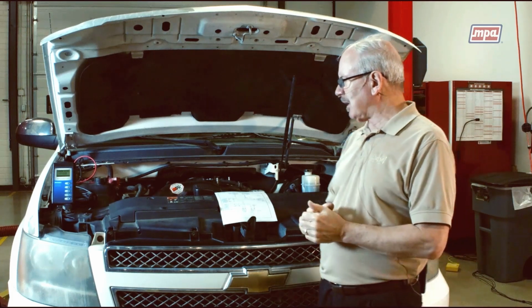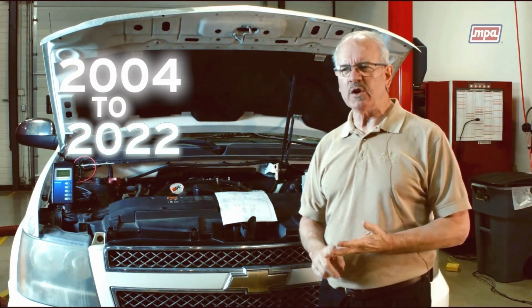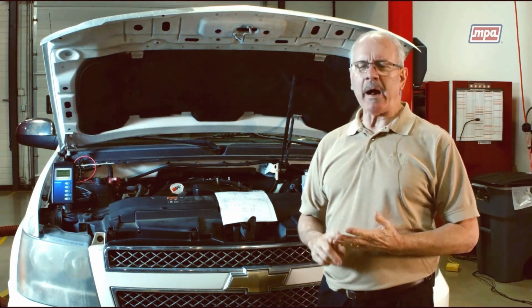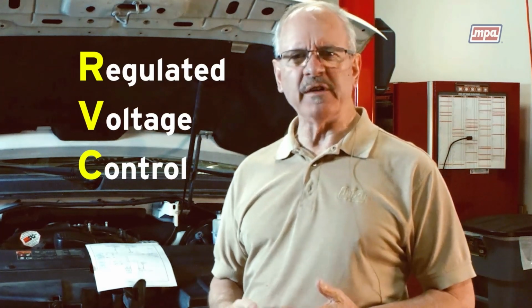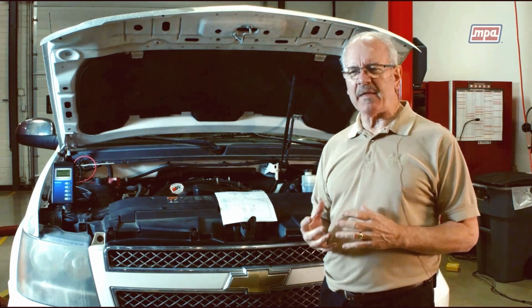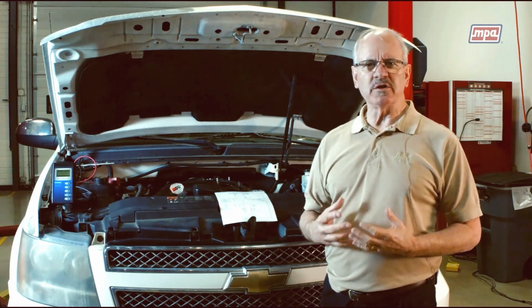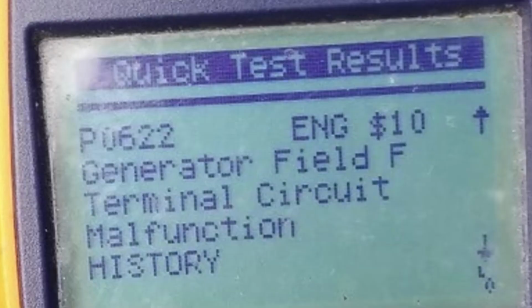Most of the GM late model vehicles from 2004 all the way up through 2022 use an electronic power management system which features regulated voltage control, or RVC. RVC is a precise method of controlling the charging system's voltage set point. The PCM, or powertrain control module, works together with the BCM, or body control module, to precisely control the charging system's voltage set point.